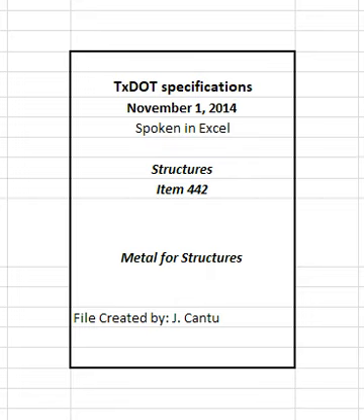For pins 4 inches or smaller in diameter for non-railroad structures, material that meets ASTM A108, grades 1016 to 1030, with a minimum yield strength of 36 ksi, may be used instead. 2.3 Steel castings. Provide steel castings that meet ASTM A27, grade 7036.